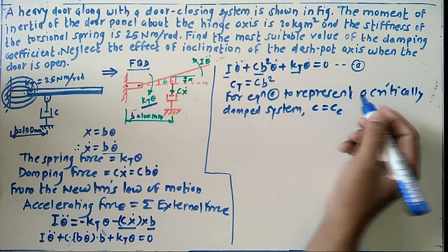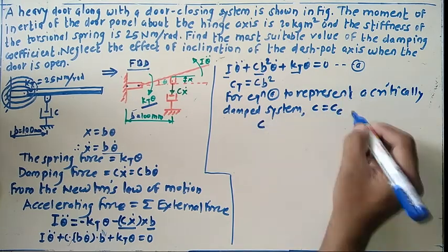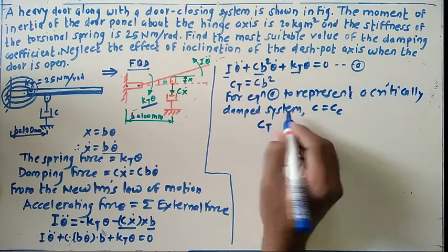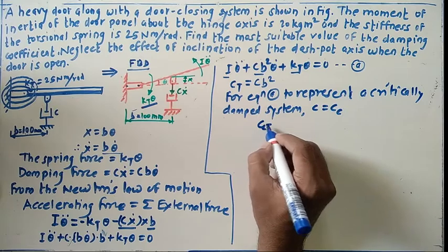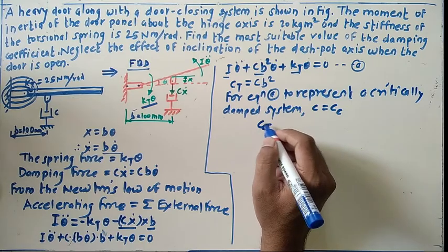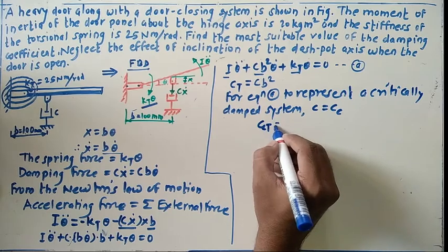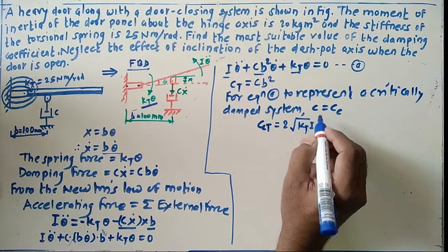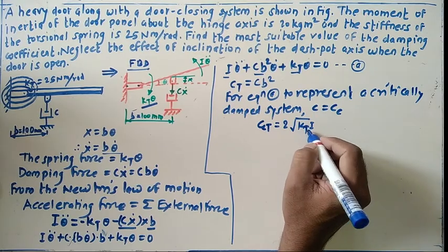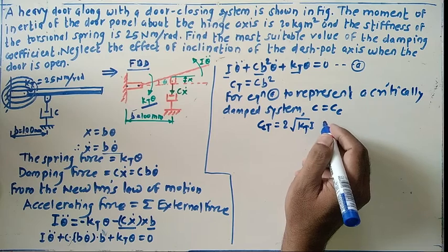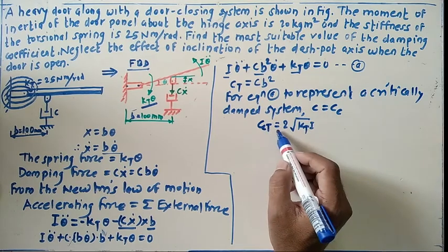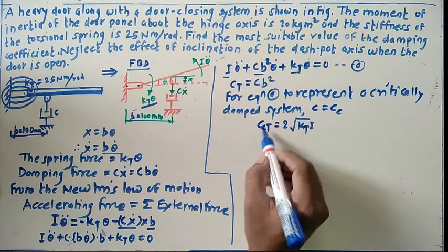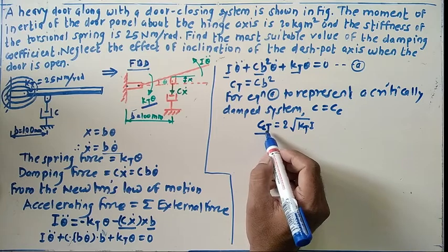Okay, so simply here we can write this term with respect to the torsional spring like this one, Cc into T. This indicates the damping coefficient for the torsional system. So we know the relation for this one, 2 into square root of Kt into I. The same relation we have seen for the linear systems. Okay, so Cc equals 2 into square root of K into M. Already we have seen that equation. So what's about this one, CCT for the critically damped system?